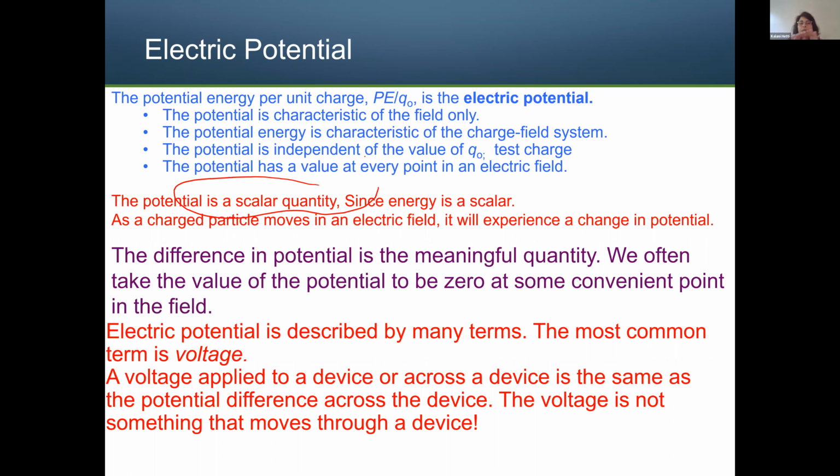Okay, so now when you come to the laboratory, we are not measuring electric potential, we are measuring the potential difference. Why is that? Electric potential difference is the potential from one point to another point. In your voltmeter, multimeter, you have two terminals. One is COM, the other one is volt. So if you use COM and volt, that means you are measuring potential difference, not the potential. You cannot measure the potential at one point by using a voltmeter, because there should be two terminals to measure it. That will be the potential difference that you are measuring.